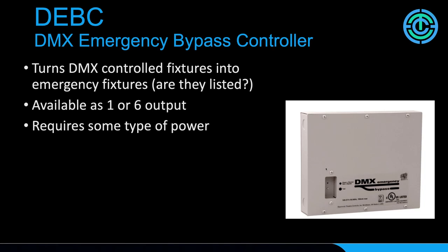It has a local test switch and an indication on the front of it as well that allows facility staff, which is a key component in this, a non-technical person, to go around during their monthly inspections and test the emergency lighting system without having to touch the main controls or have knowledge of passwords and whatnot.